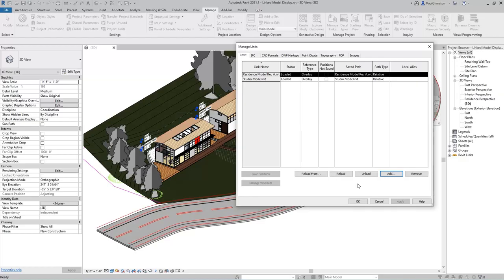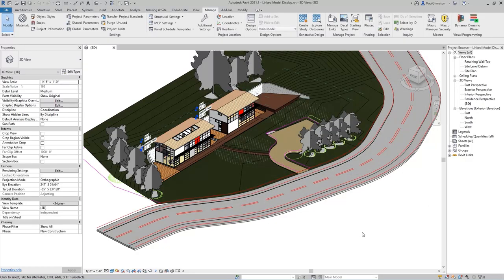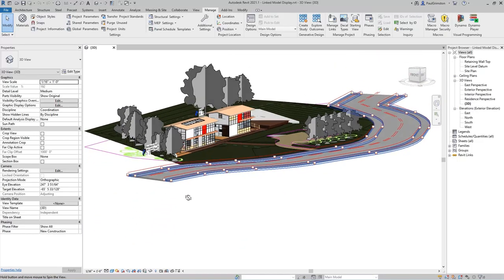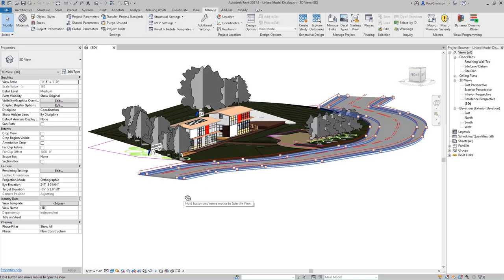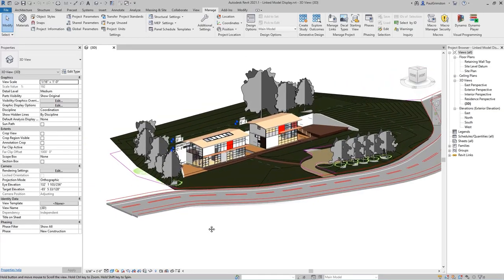within the project. So rather than unload it from the entire project, it's likely that we want to control it in individual views. So I'll choose Cancel to go back to the view. Looking at this 3D view in particular, the DWG file tends to make it a little bit confusing, as the lines are drawn in 2D and it's placed at a certain level, which is the site datum level. Whereas our 3D model changes in height as it goes along the road and across the terrain, and therefore the 2D DWG gets a little confused with the 3D model.